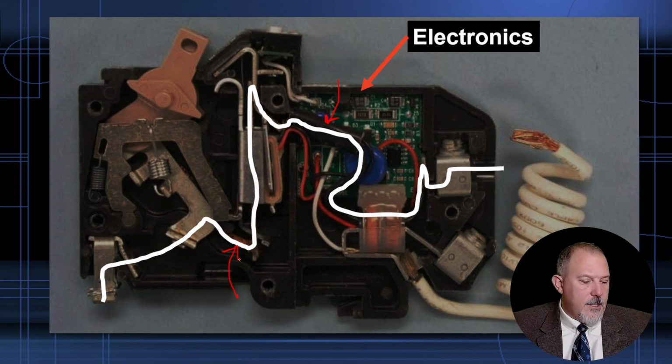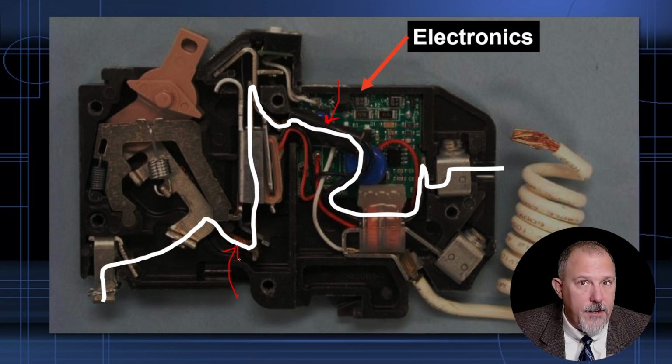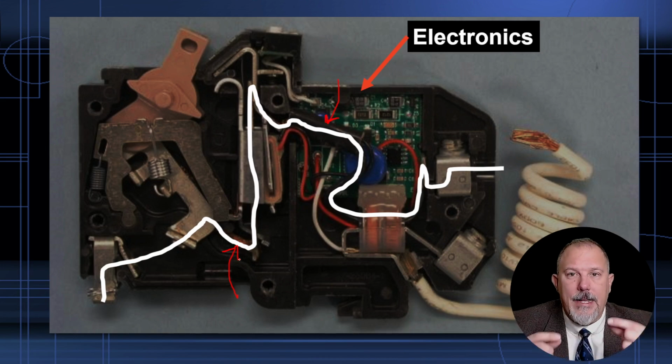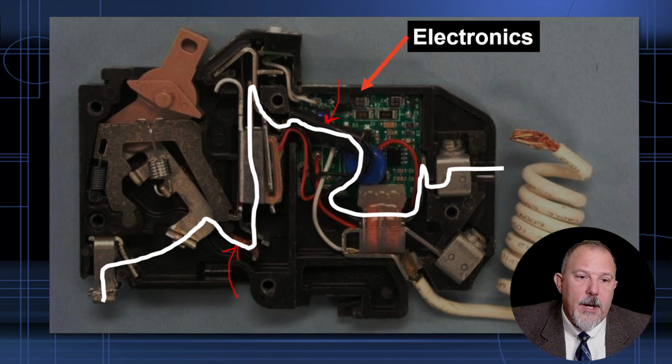That braided conductor is on the lever arm that's moving, and it has to be a braided conductor carrying current, because your contact will move. So we need a flexible piece of conductor there, and we all use a braided conductor, bare copper. That braided conductor will let the current flow up through the bimetal.